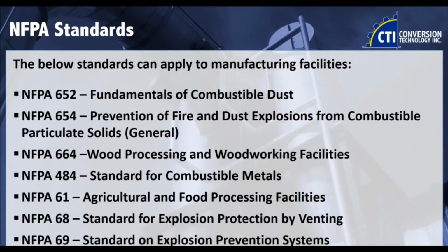But you do have commodity specific standards for wood processing and timber facilities, NFPA 664. For those of you that might deal with metal fabrication, grinding, even depending on what it is, some of the paint booths, aluminum, things like that, that's going to be 484, which is the standard for combustible metals. And then if you are installing explosion protection, for instance, you would then fall into NFPA 68 and 69, which is the standards for explosion protection by venting, and then the standards on explosion prevention systems.